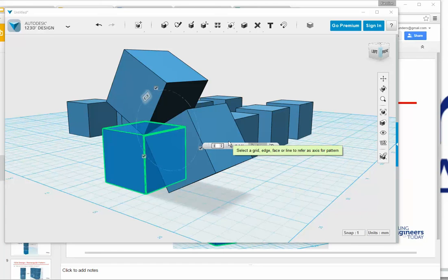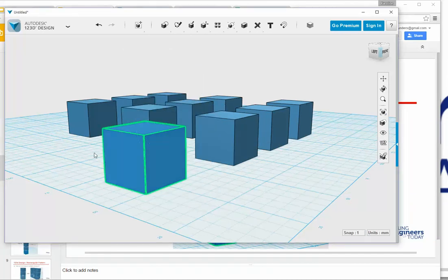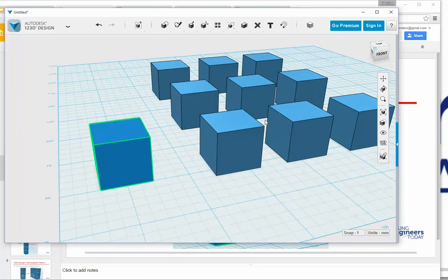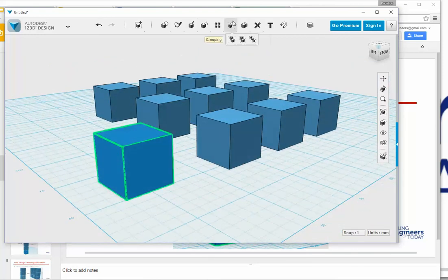To those of you who think they have mastered, can I repeat how to do it? Yes, I will repeat how to do it because I did not give a good example there. So let's start a new box just to keep it consistent. Just like before, we'll click on pattern and then circular pattern, and then select the new box we created.